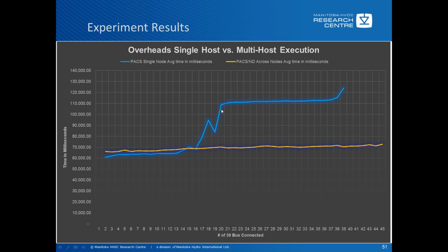But you can see at 20 CPUs, it's exactly into the hyperthreading band, and before 15, it is quite optimally loaded such that it's getting maximum performance. So this quickly tells us that while you can use a machine that's hyperthreaded to 40 CPUs, you have to expect that if you're using more than the number of physical cores, you're going to get a detriment in performance.